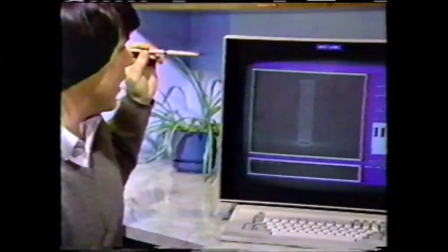I would like to demonstrate this using a sample calculation of flow around a single post between two flat plates. This is similar to the geometry in the Space Shuttle main engine, where there are posts around which is flowing liquid oxygen. Looking on the screen, we can see a representation of this single post shown here, and a representation of the flat plate shown by the grid on the bottom. The flow will be going from left to right across the screen.